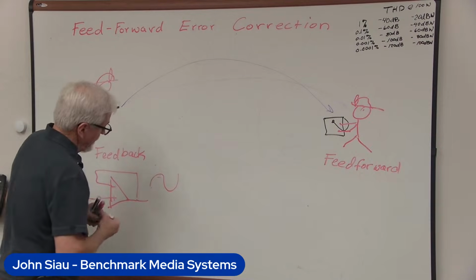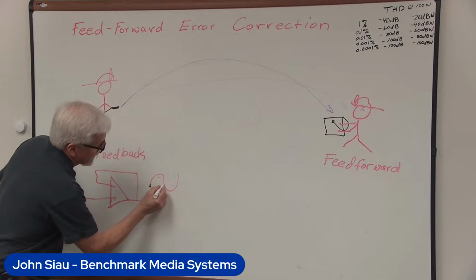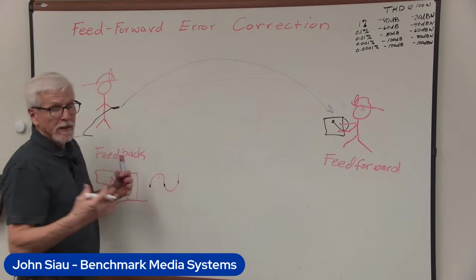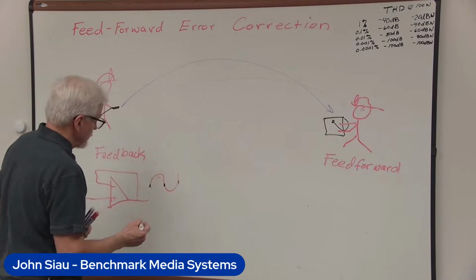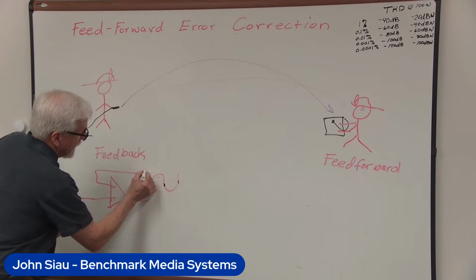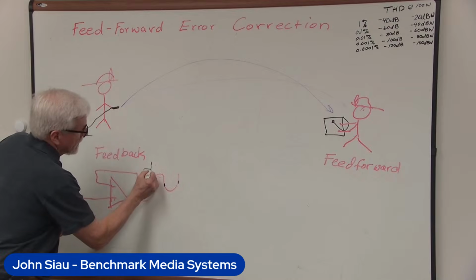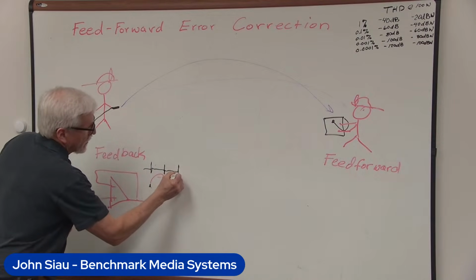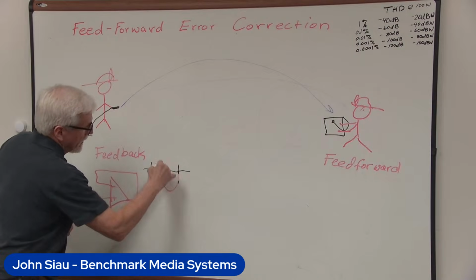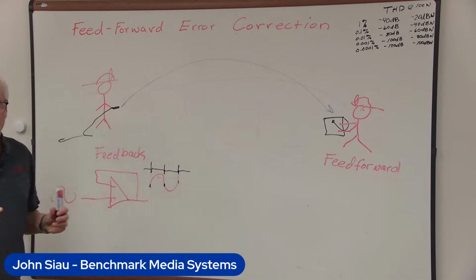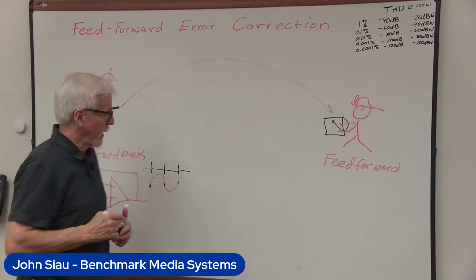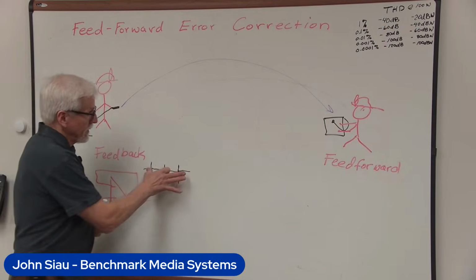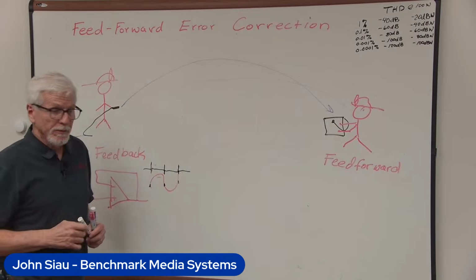Now, we might have a little bit of distortion, say zero crossing distortion. We can have other contributing factors contributing to the distortion. If we were to amplify that distortion signal, it might look like that. If we had crossover distortion, there'd be other shapes in here depending on what kind of harmonic content we have. But we have that error signal. That's the distortion that we'd like to get rid of.